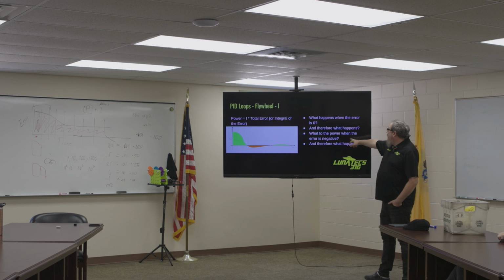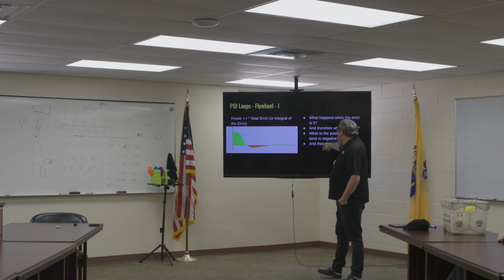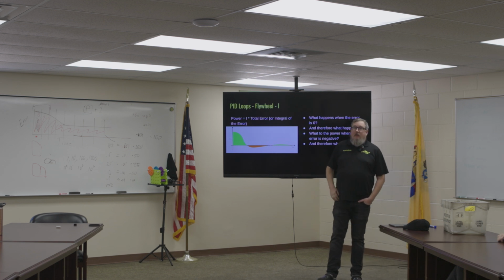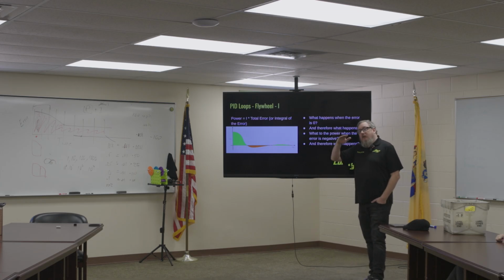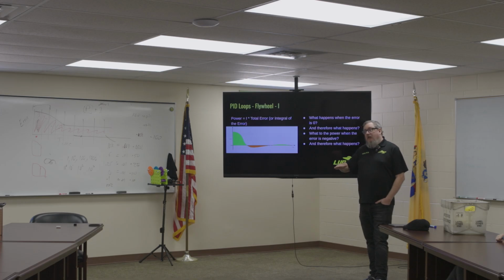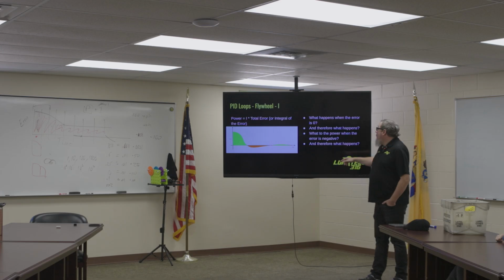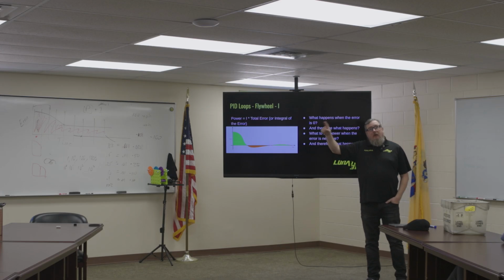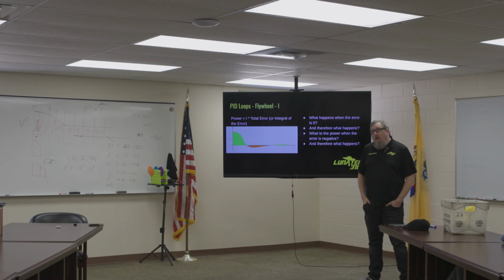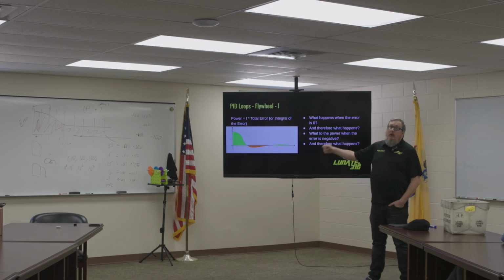If the area goes negative, what happens? The area would decrease, or does it? The area would decrease until it gets negative, because the area could still be positive even when it goes underneath, right? So you can use I to give a constant state of power, though you've got to watch out for something called integral windup, where you give it too much power, because integral will rapidly add power, and you have to be careful with that.